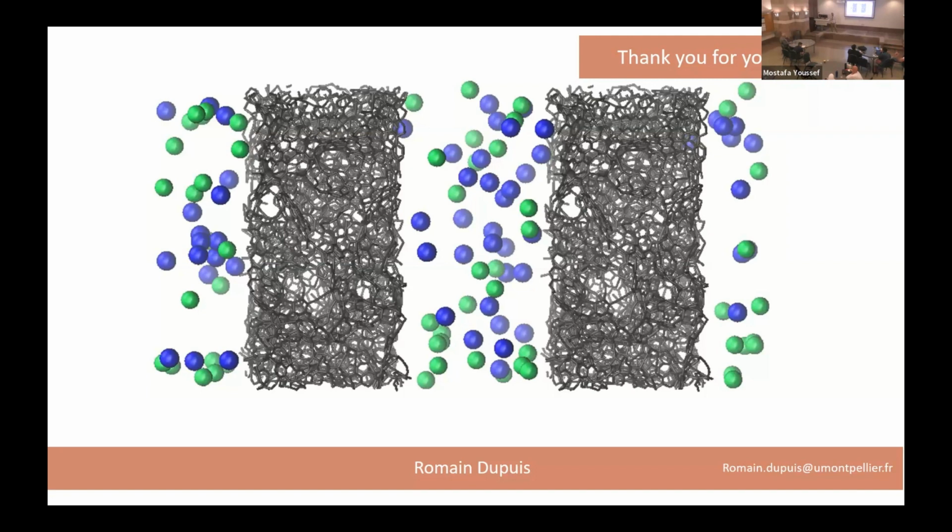And in both cases, the chemistry and the geometrical defect, they localize electrons. So that's why you see the ions getting in the pore. And if you speak about supercapacitor, the difference with the capacitor, the super, is the fact that the ion can get in the pore. If the ion gets in the pore, it is because of a defect. Yes. But the question is, if you have too many defects, then you make the carbon not conduct electricity. Yes. Then it's not an electrode anymore. Yeah. So there is a trade-off between the amount of chemistry or defect you want to help the ion getting in the pores. But too many defects means that you're killing the conductivity.